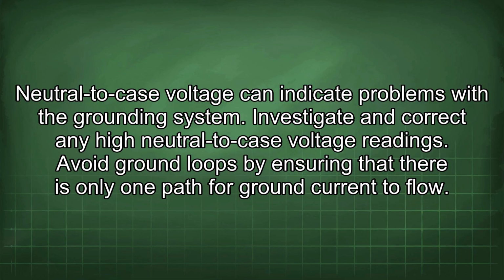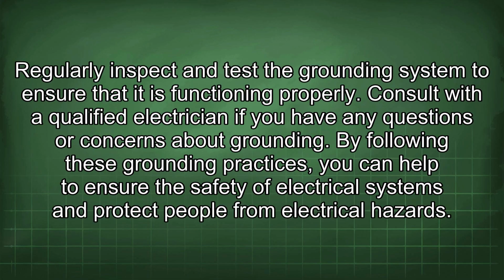Avoid ground loops by ensuring that there is only one path for ground current to flow. Regularly inspect and test the grounding system to ensure that it is functioning properly. Consult with a qualified electrician if you have any questions or concerns about grounding. By following these grounding practices, you can help to ensure the safety of electrical systems and protect people from electrical